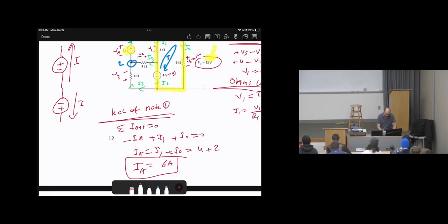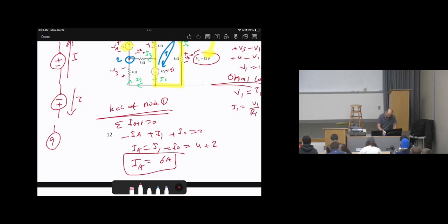And the same when we have a current source, you will assume the positive at the top of the arrow. Again, this is the opposite of the resistor because the resistor is absorbing power while the sources are supplying power. That's the justification why we have this.